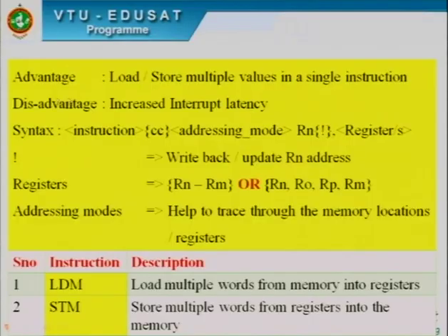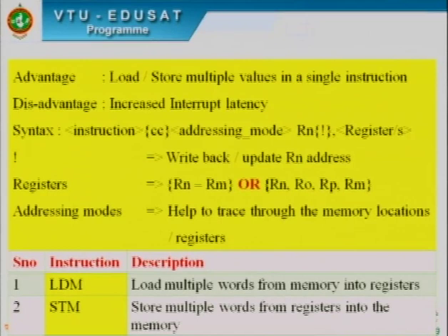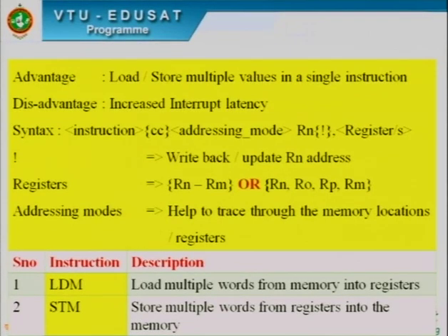The time taken to start the interrupt service routine execution from the point that the interrupt has occurred, that duration is called latency. Once these load store multiple values instructions are executing, until that instruction gets completed, the interrupt service cannot be executed. Hence, these instructions increase the interrupt latency.